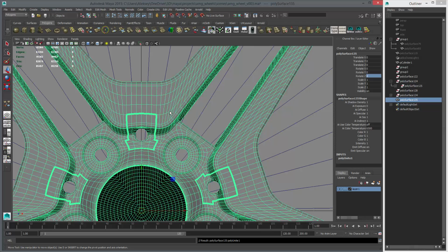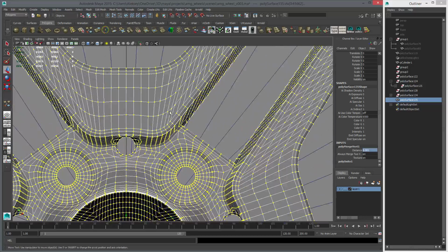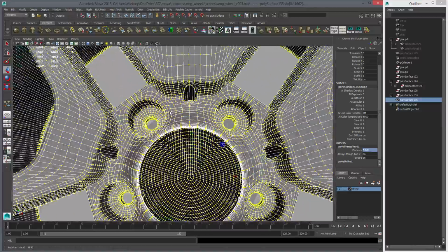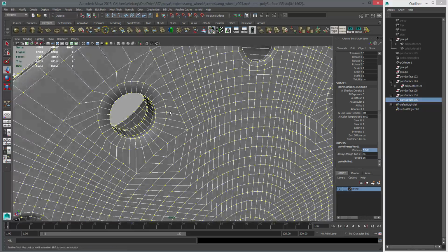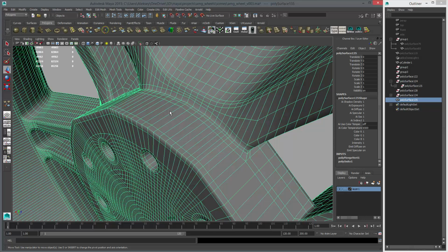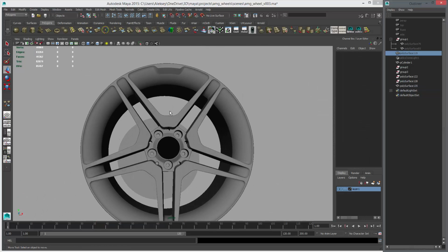And we'll combine, and I'm going to click merge, but I'm going to set the merge tolerance to really low. Let's do 0.001 to make sure that no unnecessary vertices got merged, because that'll create bad geo. Okay. Well, that's it.